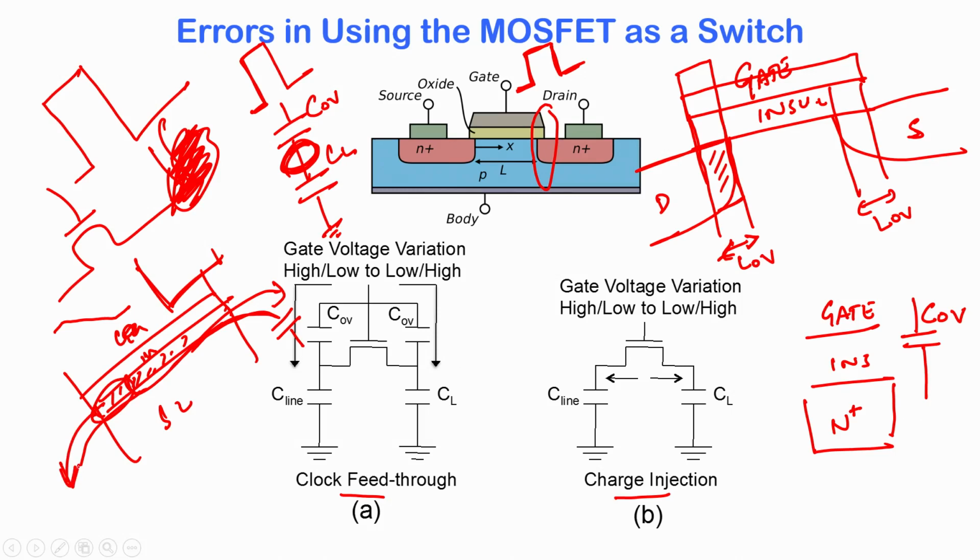Okay. Basically the charge distributes itself, you have a current that distributes itself depending on the external impedances. But on the other hand, if you were to turn off this gate very rapidly, you do not give enough time for the charge, and you will find that an equal amount of charge exits the source and drain electrodes.